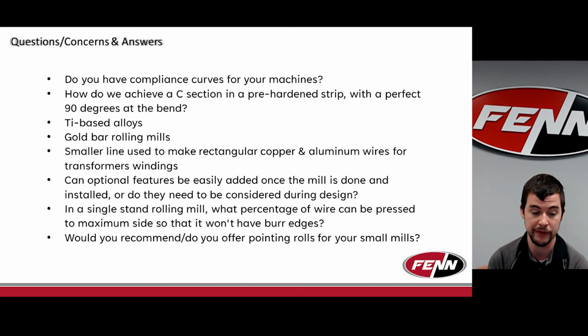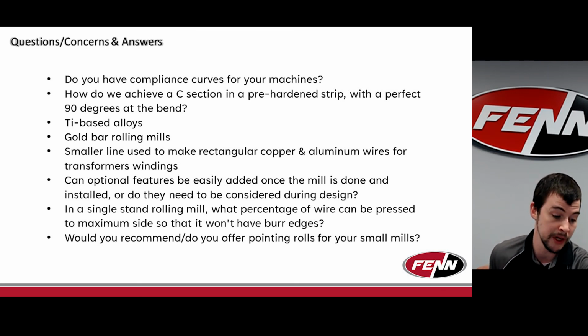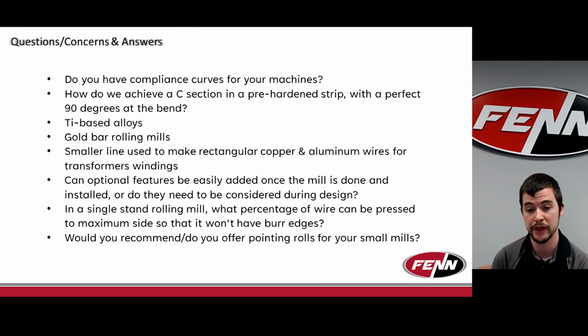With mills themselves, the generation of burrs is going to be relatively minimal because you have free flow to the sides. The key on the wire flat is how much natural spread you're trying to get from width to thickness. That's when I mentioned the idea of roll curves, where the geometry of your roll plus your thickness reduction is going to dictate how much natural spread you get to the sides.